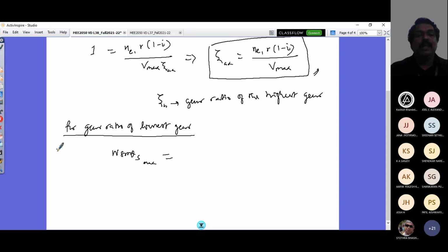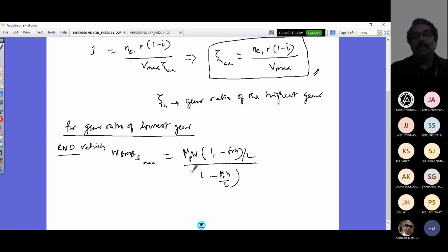we have looked at, say, let us consider for the time being a rear wheel drive vehicle. In a rear wheel drive vehicle, we have derived our maximum tractive effort expression: mu p times W into L1 minus Fr into h by L, all divided by 1 minus mu p h by L, minus Fr times W. This is the expression we looked at in the last class.